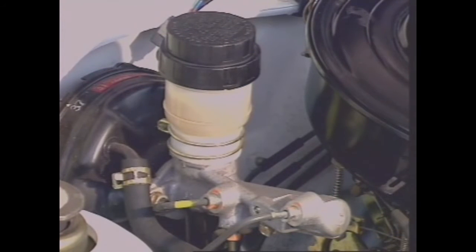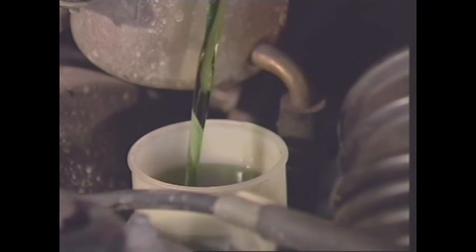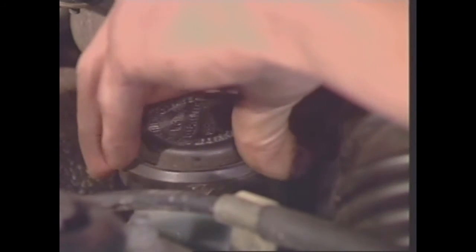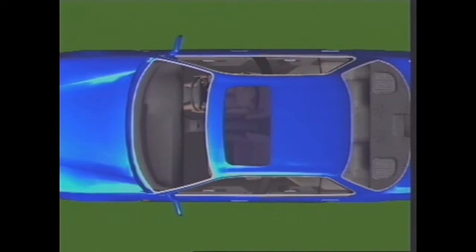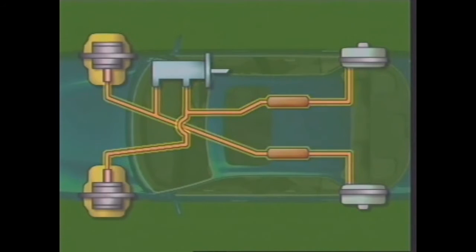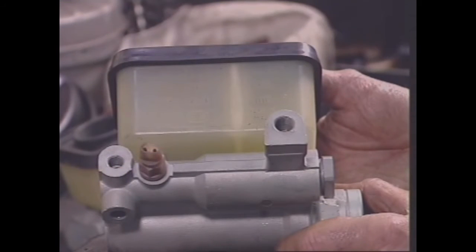With a basic master cylinder in the braking system, any loss of fluid, say because a component fails, could mean the whole braking system fails. To reduce this risk, modern vehicles must have at least two separate hydraulic systems. That's why the tandem master cylinder was introduced.